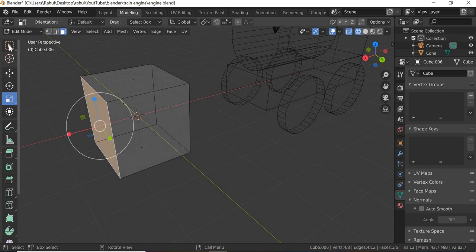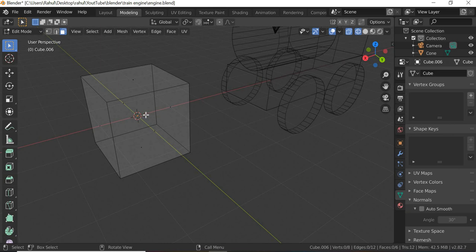So you will see in this box there are four sides to the face. There's only one line here, one line here, one line here, one line here. Alright. So it is important to understand that whenever you create any object, most of the times, 98% of the times, it should have four sides like the cube. Sometimes it can have three sides, but as much as possible try to not have five or more sides to an object. Okay, and we will understand that more in detail when we create more complex objects.